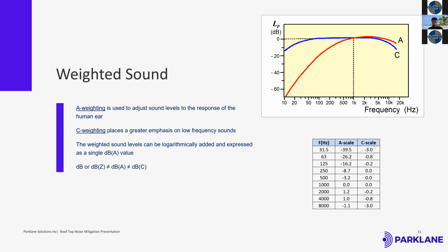Sometimes, even though the sound in the lower frequency is not loud enough for you to hear, your body can still perceive it through vibration and whatnot. In those instances, they would use something called a C-weighted scale. These are the two common weighted scales used in industrial practice. I just wanted to give you a brief pointer on that.